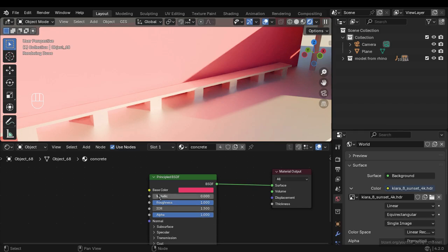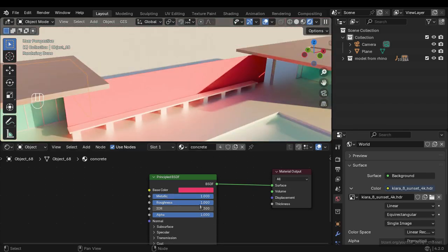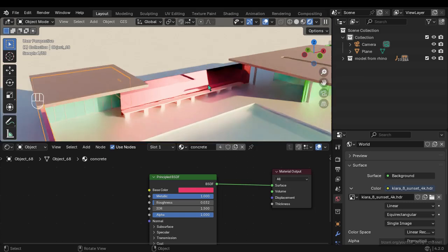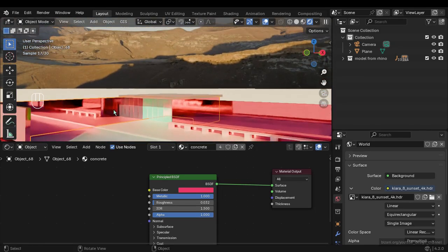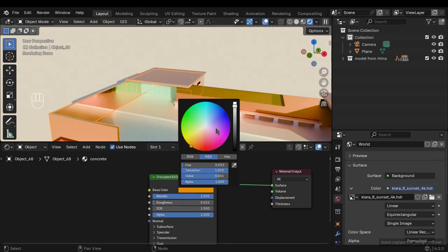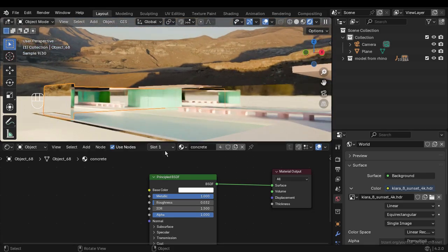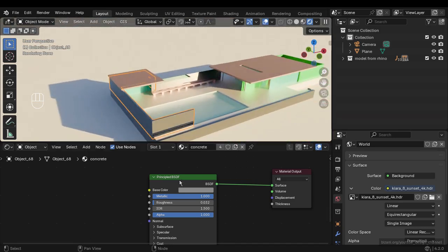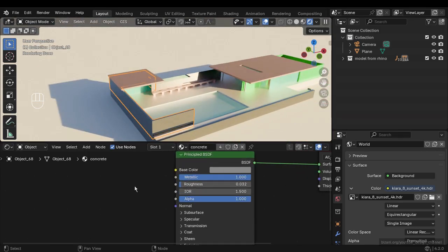Here we can control the metallic value, which is only useful when we have low levels of roughness, so the material reflects more. With the diffuse material, there are more reflections, and we can have a goldish material using this way. Or we can make mirrors if we decrease the saturation in the color, so we have that mirroring effect, or we can have a darker mirror. This is basically what we do. So what a PBR material is, those textures that will come here will be inserted in those. And the alpha channel is the global transparency.